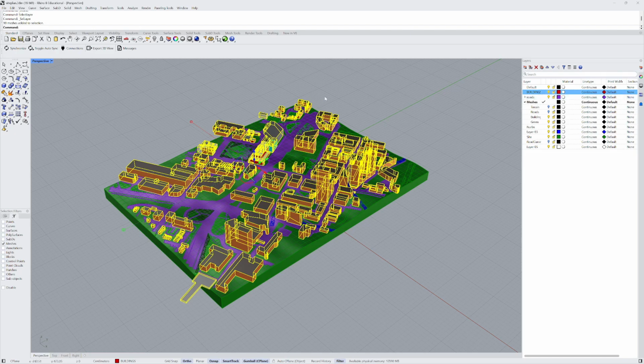The next step is I go to my NURBS here, and I'm going to create some sublayers again. Just create buildings, and create another one which is going to be terrain, then another one which is going to be roads, and then another one for the green spaces, for example. Okay, so now I have these buildings selected. I go over here to my meshes and change the object layer. So now they're in the meshes layer.